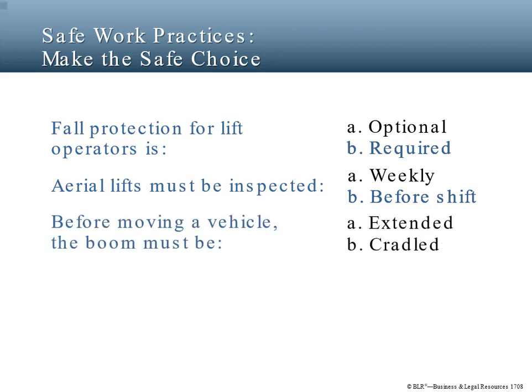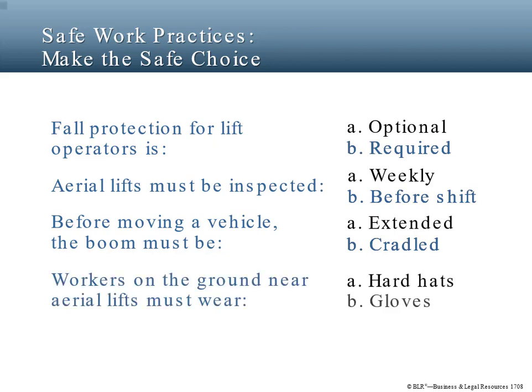Before moving a vehicle, the boom must be A. Extended, or B. Cradled. The correct answer is B. Cradled. Otherwise, the vehicle could tip over. Workers on the ground near aerial lifts must wear A. Hard hats, or B. Gloves. The correct answer is A. Hard hats, to protect their heads from falling objects. How did you do? Did you get all the answers right?